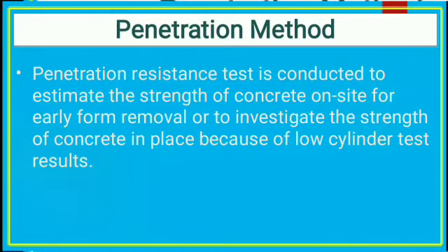Penetration resistance test is conducted to estimate the strength of concrete on site for early form removal or to investigate the strength of concrete in place because of low cylinder test results.